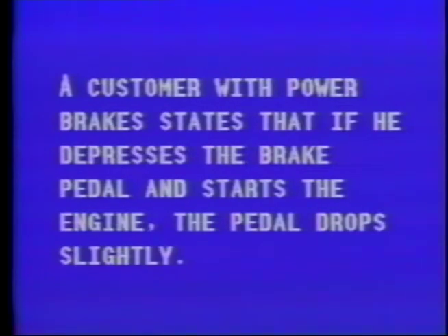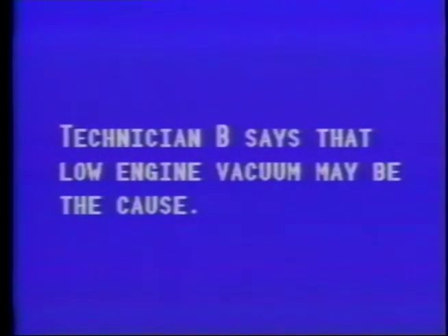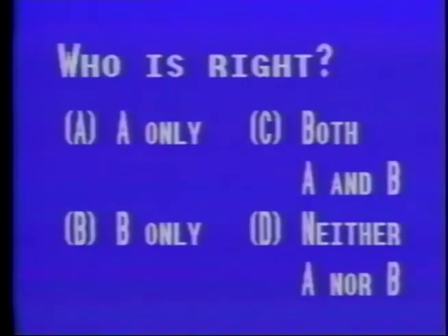A customer with power brakes states that if he depresses the brake pedal and starts the engine, the pedal drops slightly. Technician A says this is normal. Technician B says low engine vacuum may be the cause. Who's right? A only. B only. C, both A and B. D, neither A nor B.